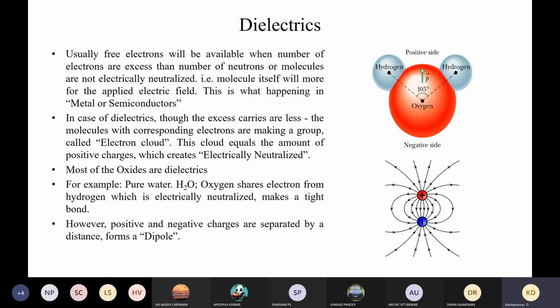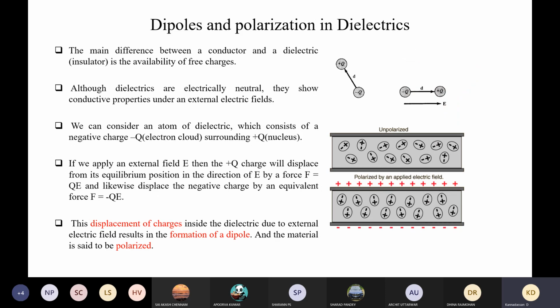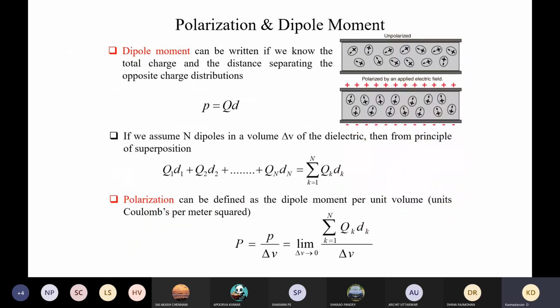The dielectric material works with the phenomenon of dipoles, and the dipole is going to induce an internal field. That is always referred to as the dipole moment. With the accumulation of dipole moments, we get a field, and that field per volume creates a polarization charge density. That is going to produce an electric flux density. So that flux density we call polarization. It is very much the same as the electric flux density.